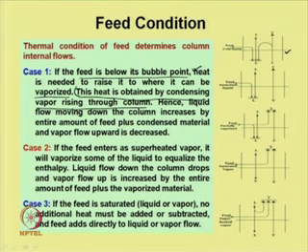So, what is happening? If we give cold feed, all the feed will flow down along with some part of the vapor which will be condensed. So, from the feed tray the internal flow downwards will be increased, whereas the vapor flow towards the top of the tower above the feed tray will be decreased.